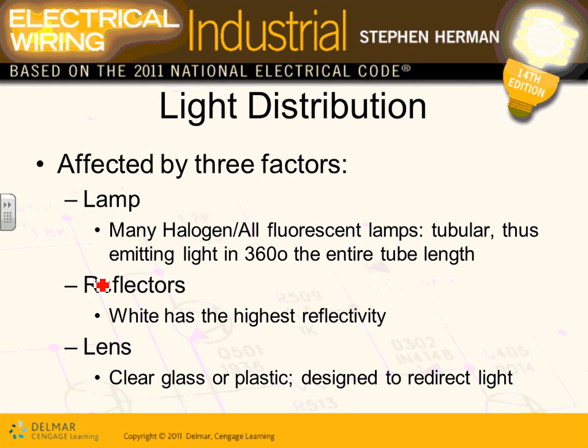Okay, light distribution. I want to remind you that we did a whole semester about lighting. The single most important thing, look above your head or outside, is the lamp. What type of lamp are you using? Are you using high intensity discharge? What type and shape of lamp? Fluorescent? How are they sending the light in 360 degrees, tubular fluorescent lights? So the type of the source, high intensity discharge, LEDs, and the shape of the fixture, that's the most important thing. And we decided that outdoor, we're going to be using LEDs.